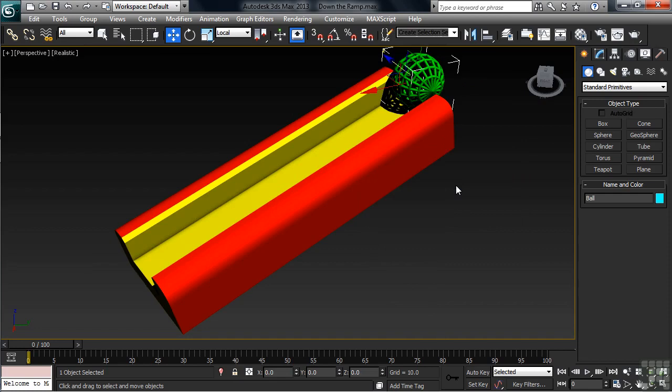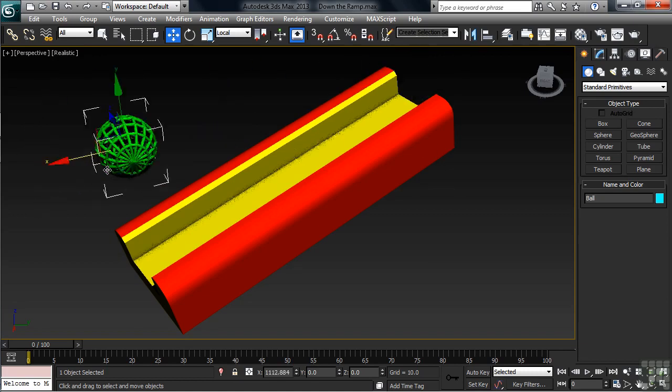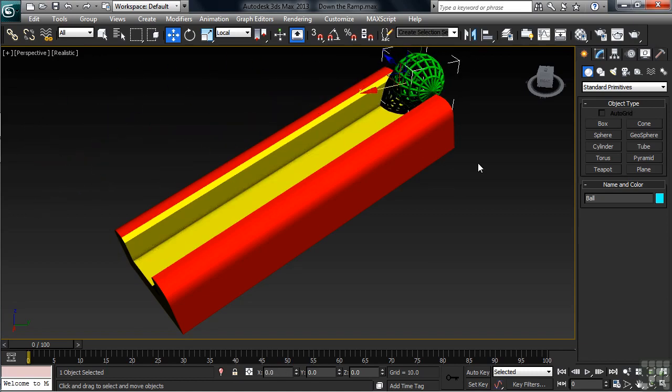Now the sticks appear to be going in the direction of the ball, which from this angle almost looks like the direction of the ramp. Let's try red and see what happens. Well, we're going in the correct direction, but watch this. Go ahead and select the ramp real quick. Now once you do that, watch the way the sticks align themselves with the ramp. The blue or Z direction is actually the direction that we want our ball to move in.